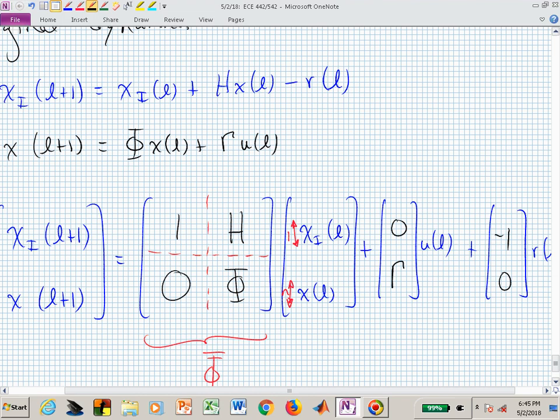So now you have a phi bar and a gamma bar. And you can use that just like you had phi and gamma before, and you'll find a K matrix that's n plus 1 columns wide. You'll pull out n of those to give you the K hat, and one of those to give you the K sub I.